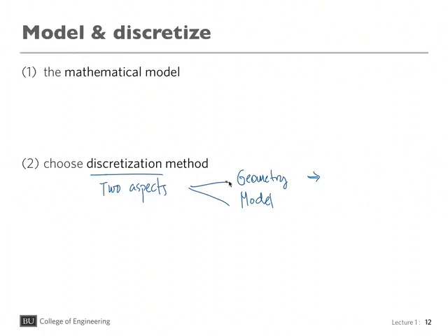The traditional way to discretize the geometry is what is called a grid or a mesh, but there are others. For example, particles, which are not very common, but the most traditional one is the grid. It's very important to realize that the outcome of a CFD simulation is very dependent on both the discretization of the geometry and the model, the method that is used, the accuracy of the method, and also the way that you discretize, for example, how fine the grid is, how it conforms to any bodies or shapes or objects that exist in the system.